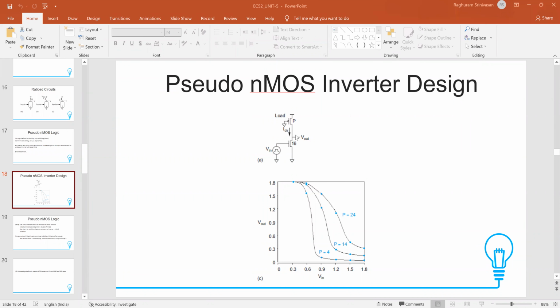So in this particular family, we're going to use that idea and try to design the circuits such that, when both the pull-up network and pull-down network are conducting... Suppose only the pull-up network is conducting, that is, the PMOS is permanently on, which is true all the time. But suppose I give the input such that the NMOS network is not conducting. Very simple: in this case, suppose I give 0, the NMOS network is not conducting. Then the output will be at the perfect value, which is the power supply. And that's what you see in the graph also.